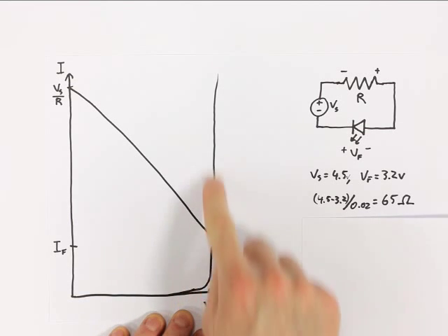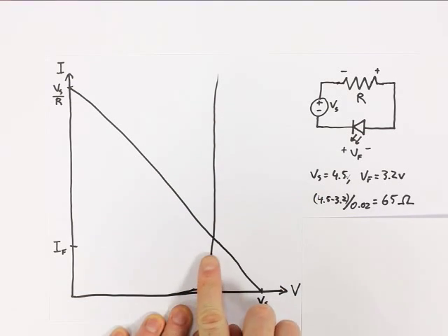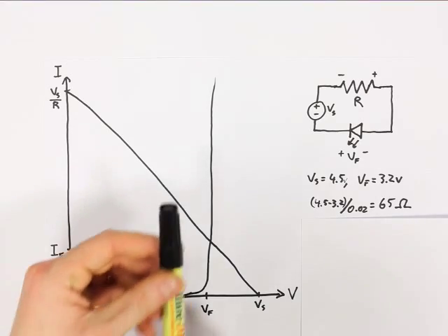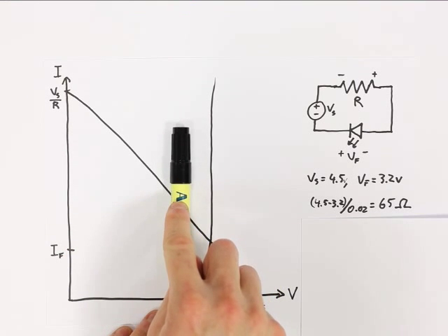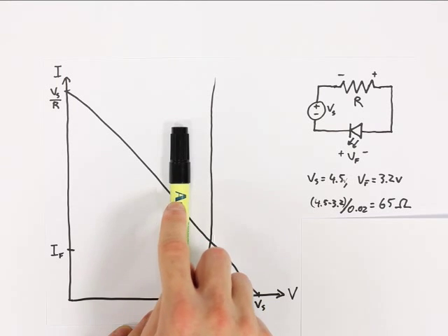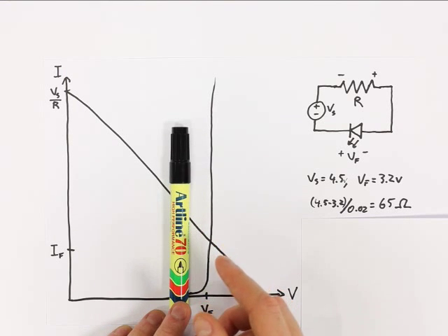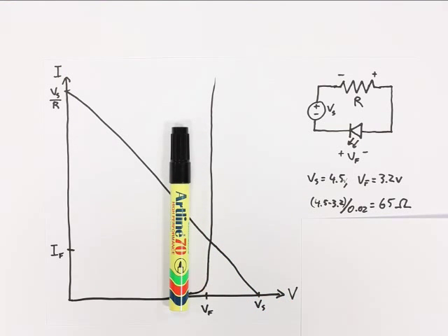And if we take this line here and shift it to the left, like this, you can see that the intersection point is rising. So IF is increasing, you're getting more current than you'd actually designed for. So if you designed for a forward voltage of 3.2 volts and your device turned out to actually have a forward voltage of 2.8 volts, you could potentially blow up the LED.